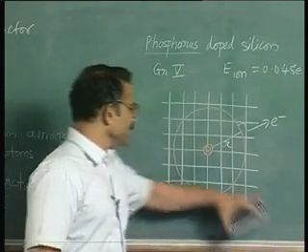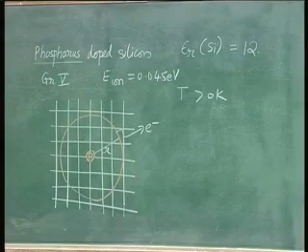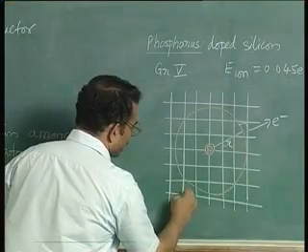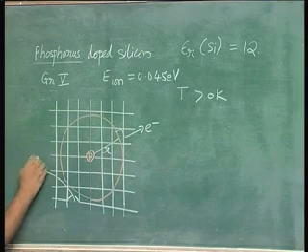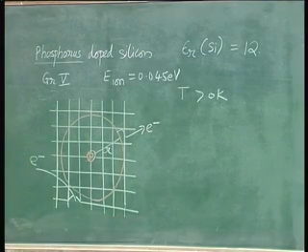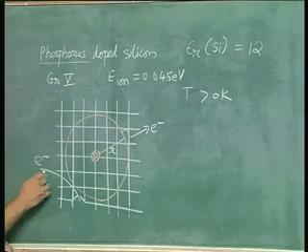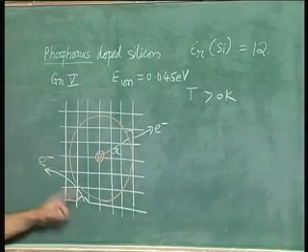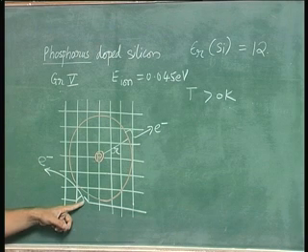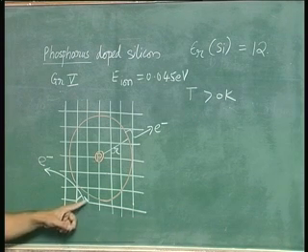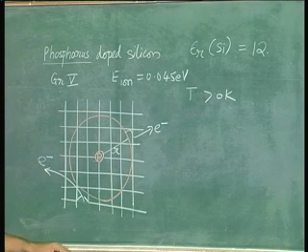But as you raise the temperature, it is also likely that some silicon to silicon bond will break and give rise to a free electron. Now this process is electron hole pair generation, because a broken silicon bond, we have said already, is a vacancy or a hole via which the bonded electrons participate in conduction.